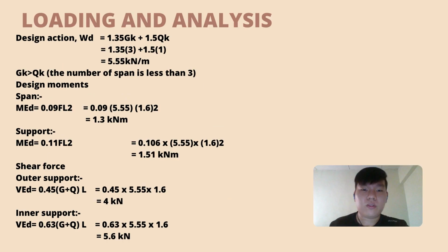And then the loading and analysis for continuous beam, the design action WD is 5.55 kN per meter, and the shear force is 4 kN in the outer support, and inner support is 5.6 kN.